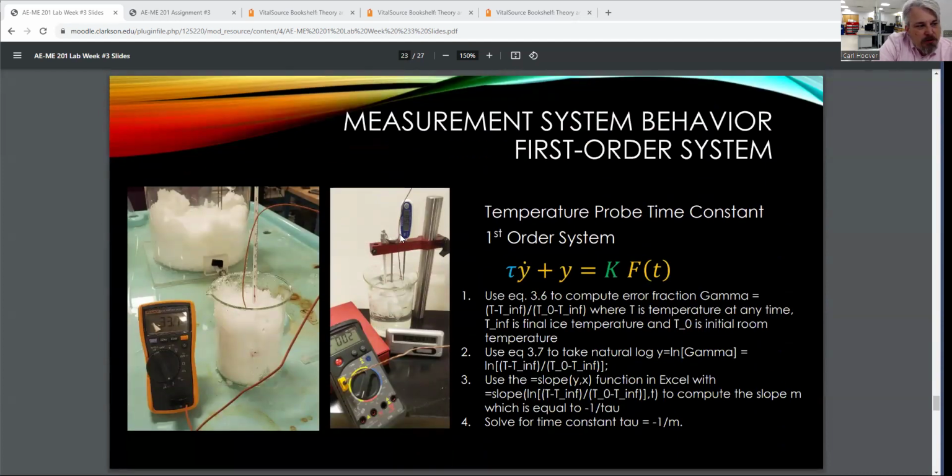Specifically, we have some temperature instruments here that we're going to plunge into an ice or a snow bath in a beaker. And we're going to track those over time. The best way to do this is actually to record a video with your phone. If you are good at videography, you can capture all of the instruments' response at the same time, or you can run this experiment with each different temperature instrument one at a time to really be able to see the response over time. It does require some post video processing to go back through and record the time and temperature at various steps.